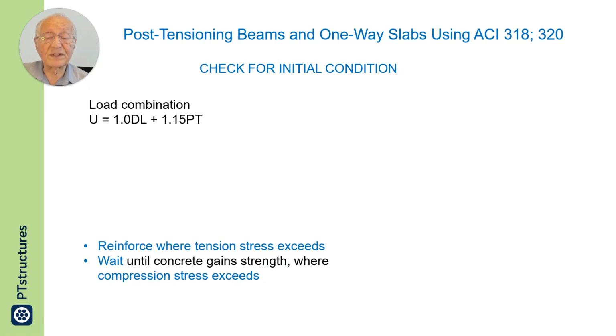You reinforce where the calculated extreme fiber tension exceeds the allowable value. You wait until concrete gains adequate strength where calculated extreme fiber compression exceeds the allowable value.